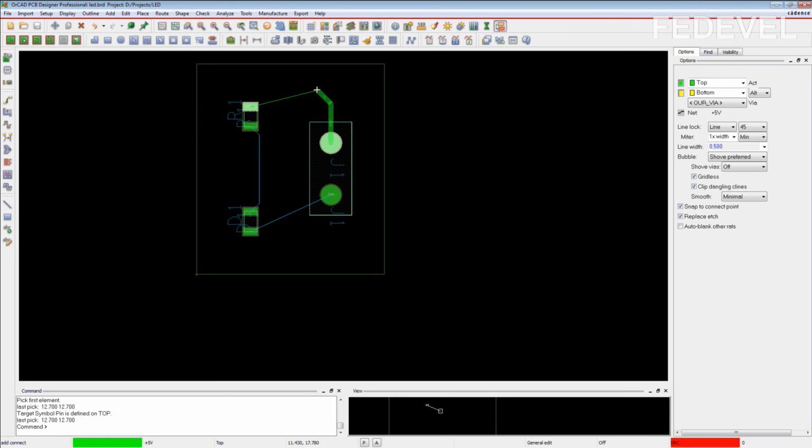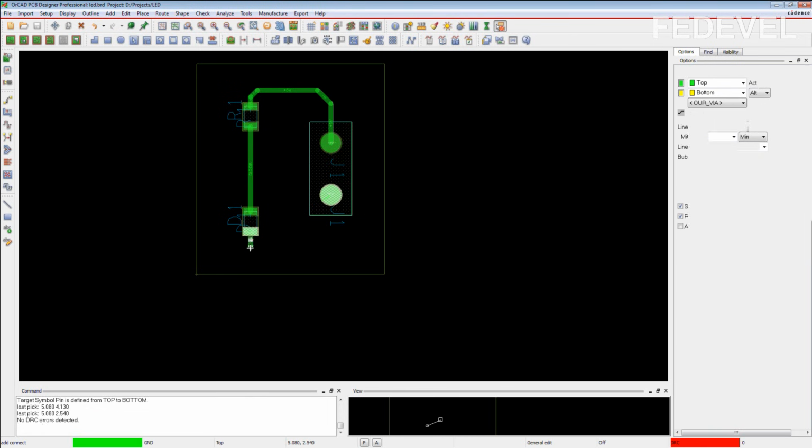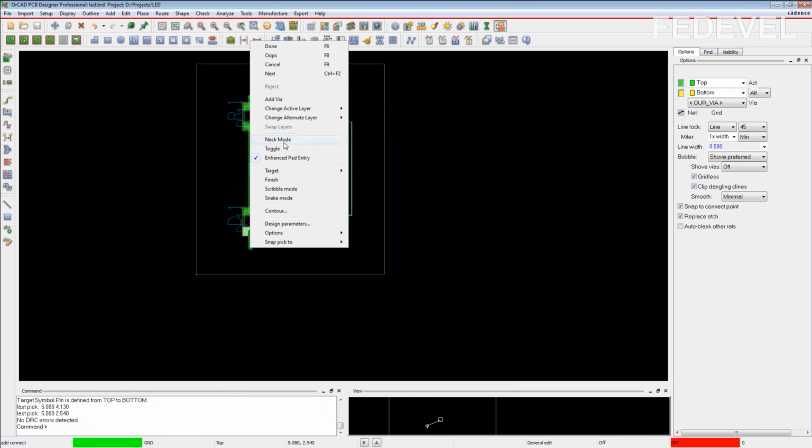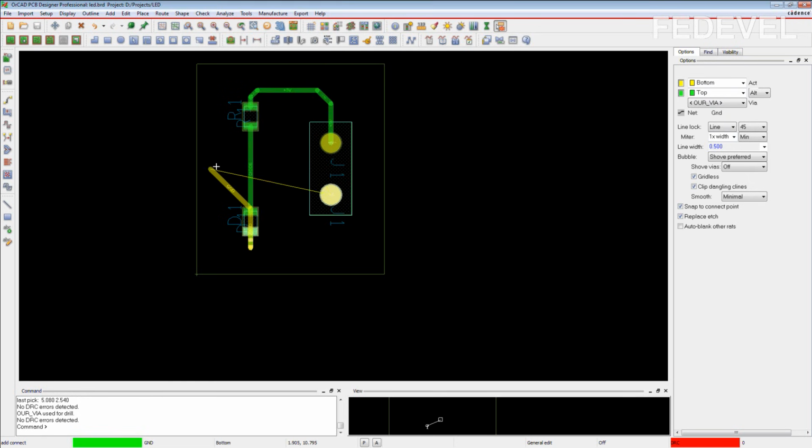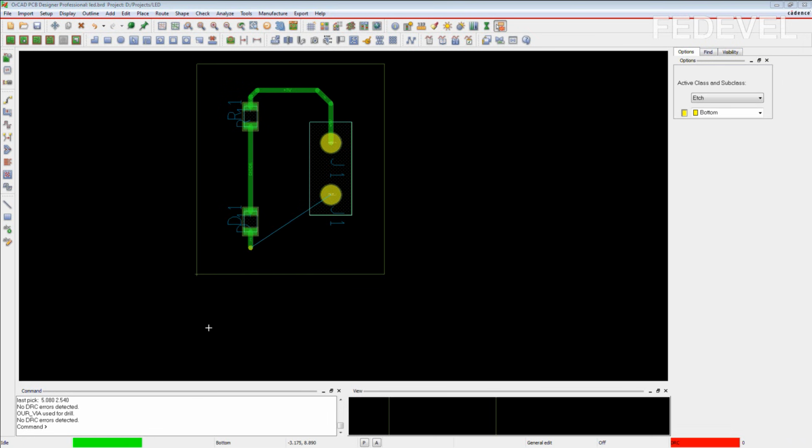Okay, left click on your mouse, left button, connect to path, left button, and here I'm not going to connect it here because I would like to show you how you can draw polygons and how you can place vias. So just click, press left button on your mouse, now right button on your mouse and add via. The via which will be used, you can see it here, it's our via. Yeah, so I just add via and right click, done.